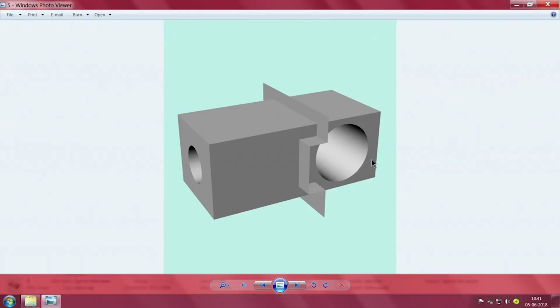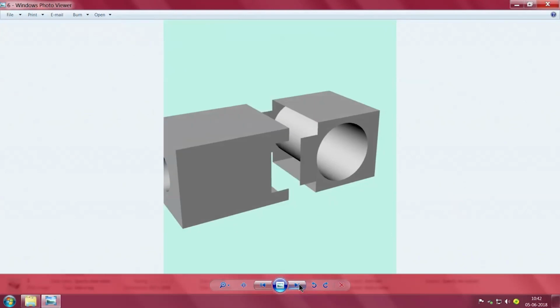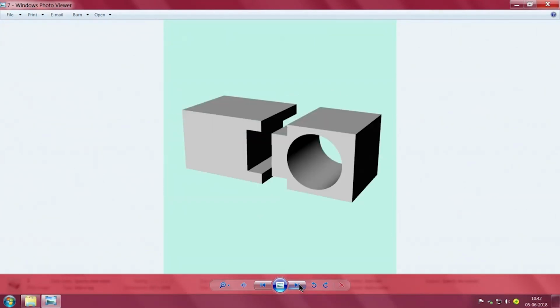So what has been suggested is you cut it into two parts. This is what I was trying to tell you in the previous session. Now you see here I have made a hat-section-like thing such that I now split the object into two parts. After splitting it, this part can be built with this face down. This part will be built with this face down. So we have no necessity for any build material to be coming inside. So if you see here, it has been cut in this place and we have this like this. Easy, is it not?